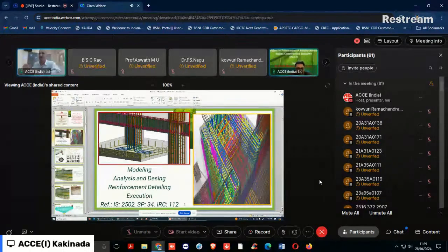And one more thing: whenever we are doing seismic resistant designs, consider the steel in the footing embedment, that is the column rebars. The column rebars are starter bars going from the top of the second mat of the footing steel. Generally, these will be from the top of the footing to the end of the starter bar. This should be the development length in compression as specified in the code.